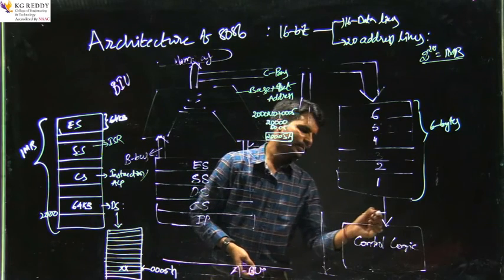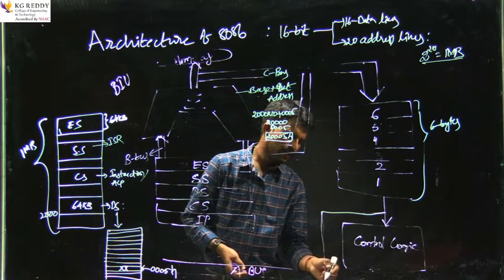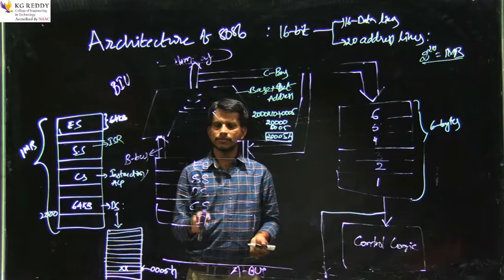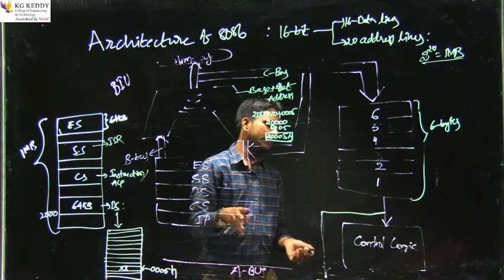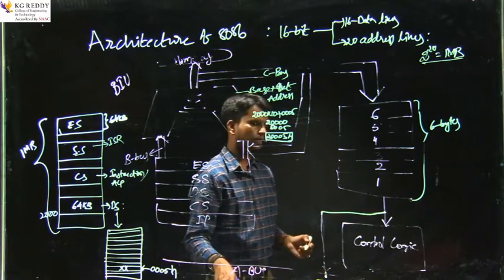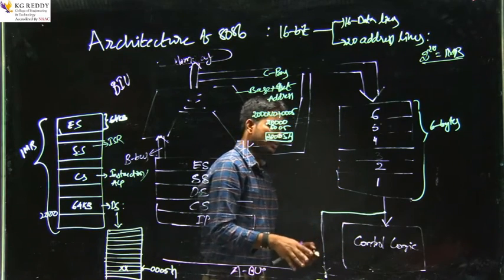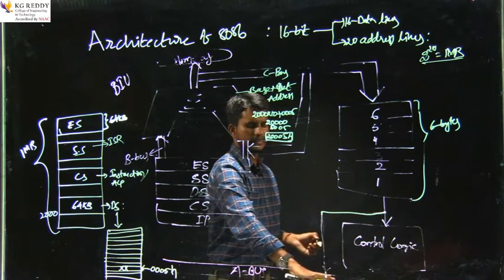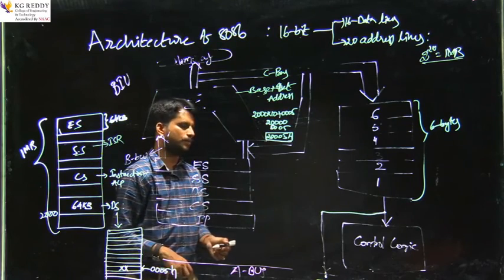And why are we using two different pathways here? One may go directly to execution and another set of instructions goes to control logic. There is a set of instructions which are system related, and they are already in decoded form. Only the set of instructions which we need to decode will go to the control logic, get decoded, be converted into machine level language, and be sent to the execution unit for execution.